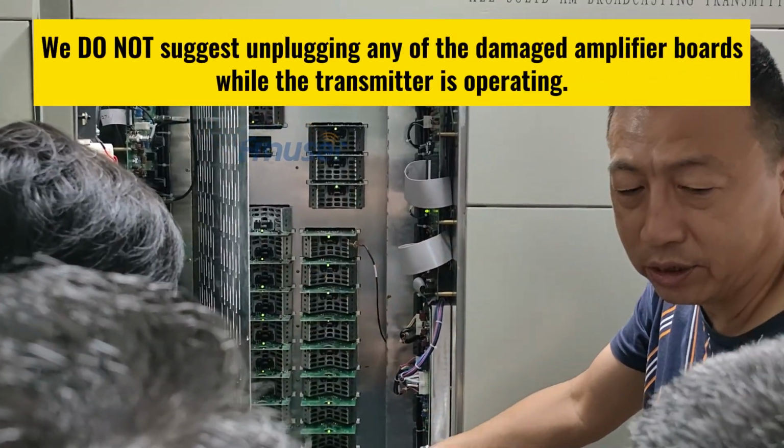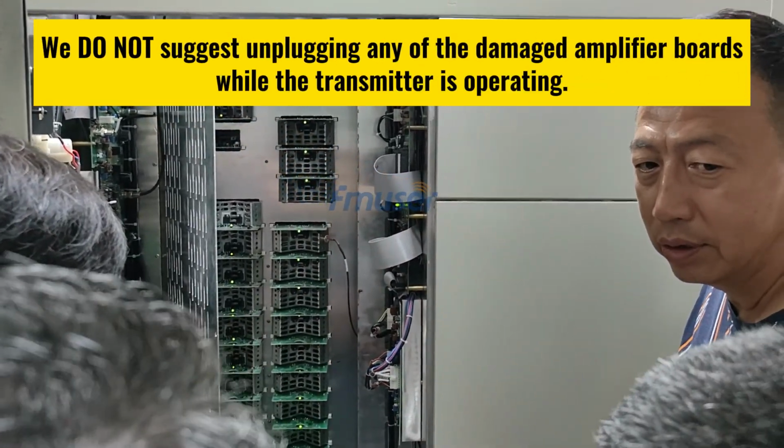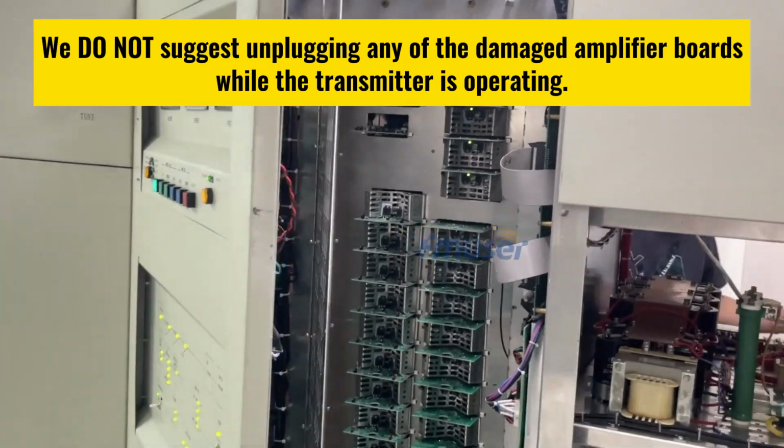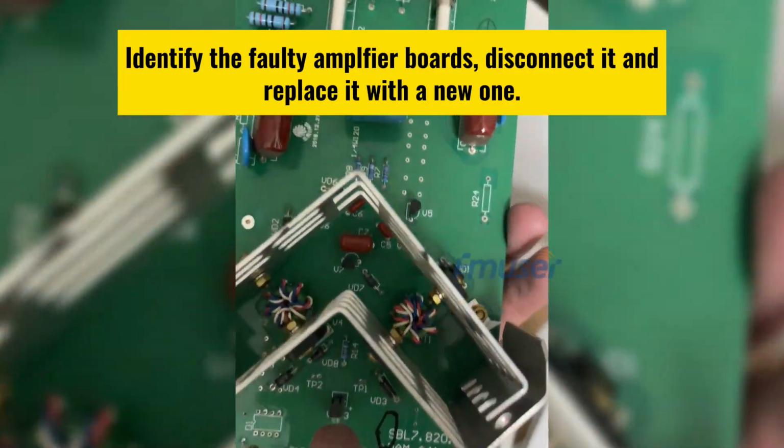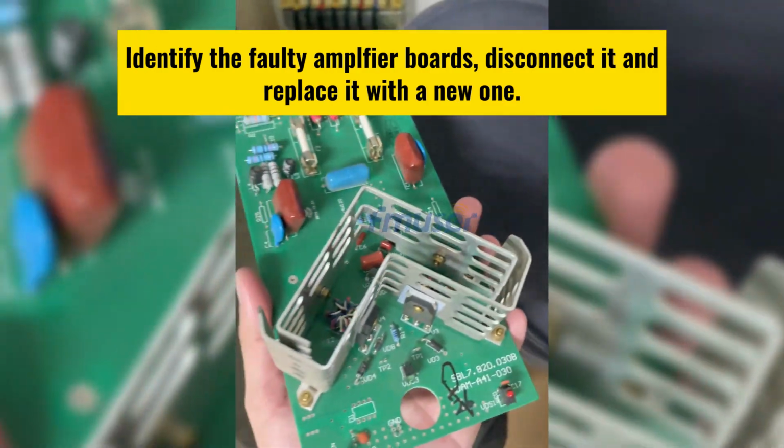It is crucial to note that attempting to unplug a damaged power amplifier board while the transmitter is operational can cause irreversible damage. To address this issue correctly, it is important to first turn off the transmitter's power. Then, identify the faulty power amplifier board, disconnect it, and replace it with a new one.